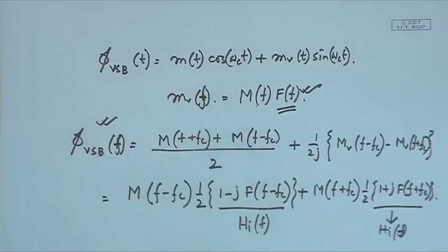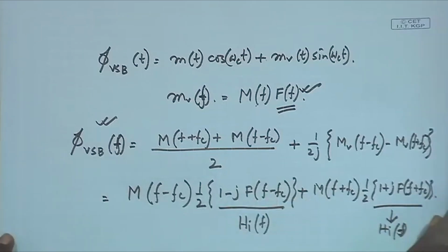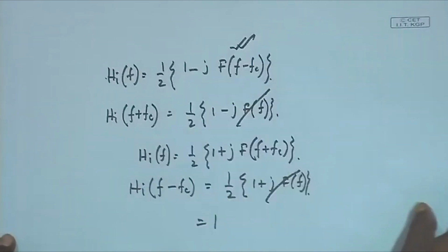I can also see if I just multiply this by 2 cos omega_c t, immediately I get my signal back, because I multiply by 2 cos omega_c t, put a low pass filter, and I will get my m(t) back. That is consistent. Earlier also we have proposed the same thing. So, with this particular thing we will always be getting back the signal, right.